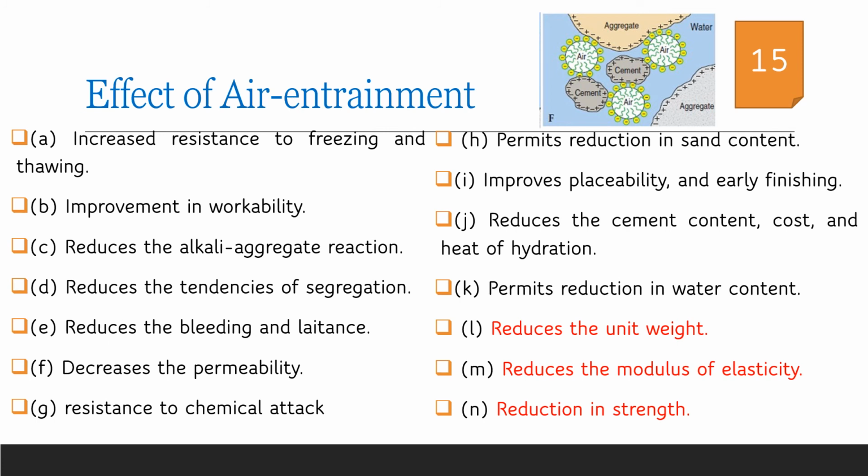As a result, the following effects are observed in concrete. It increases the workability of concrete. Also, there will be less tendency of segregation and bleeding. It also reduces the permeability and increases the resistance to chemical attack. It also increases the resistance to freezing and thawing effect. It permits the reduction in sand content as well as improves the placeability and early finishing. It permits reduction in water content. These are the positive influences of using air entraining agents.